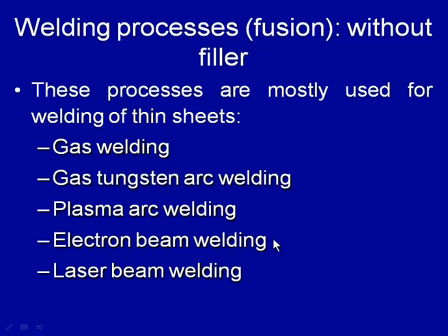But electron beam welding requires the vacuum, because when the beam of electrons moves through the atmospheric air in ambient conditions, the velocity is reduced very significantly, and the beam is not able to generate enough heat to bring the faying surfaces to the molten state and to produce the weld joint.